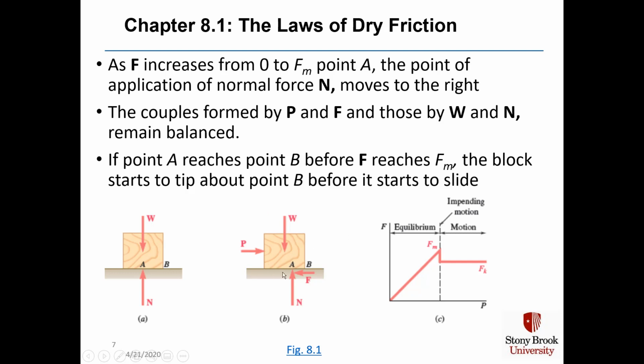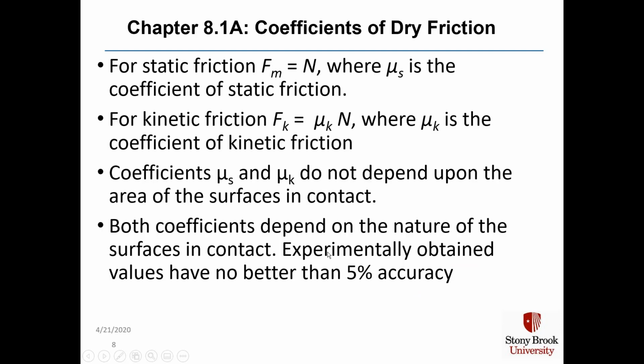that goes counterclockwise. And if point A reaches point B before force F reaches its maximum, the block will start to tip about point B before it starts to slide. So this whole block would actually start to rotate around point B rather than slide along.